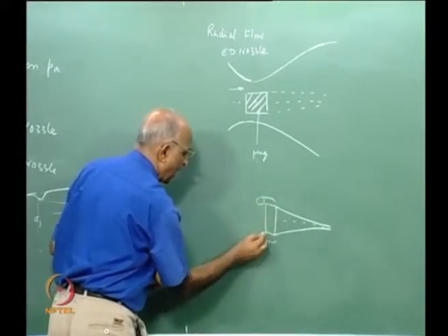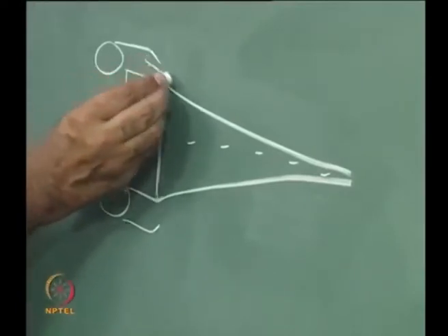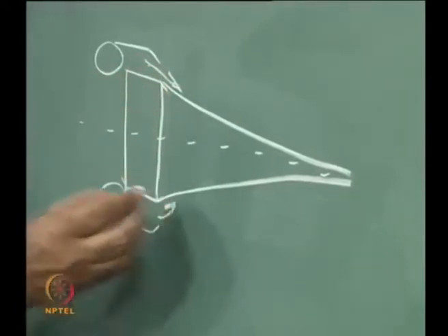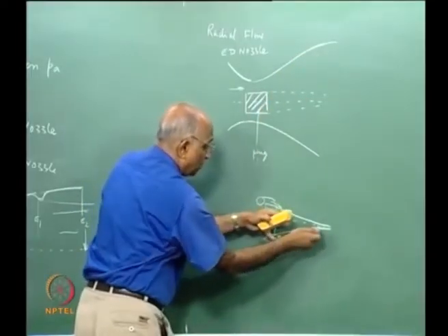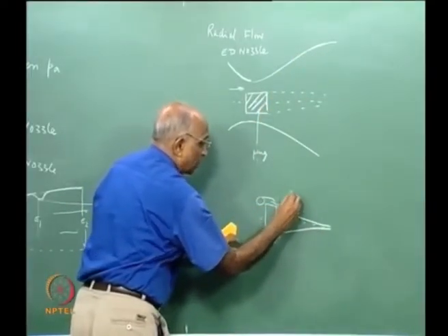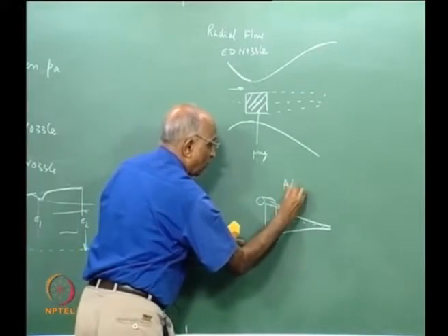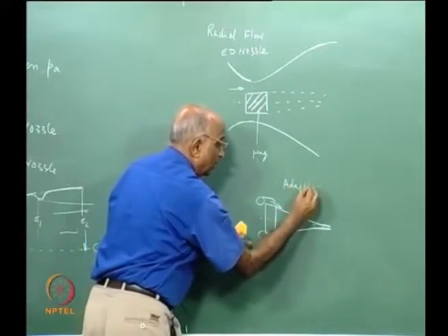In other words, I have an annular chamber over here, I allow the flow to come across this, I allow the inner contour instead of the outer contour to balance the flow, and keep the outer open such that it is again a case of an adapted nozzle, it can adapt to any condition.